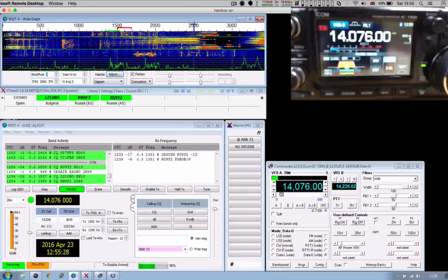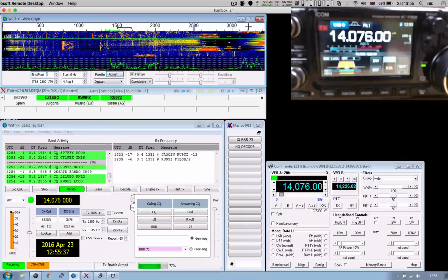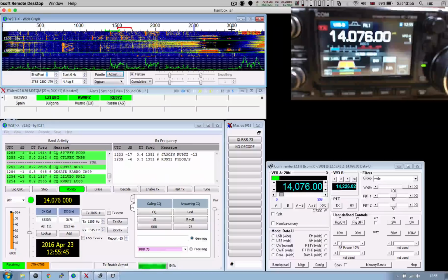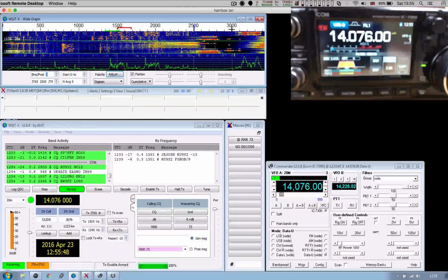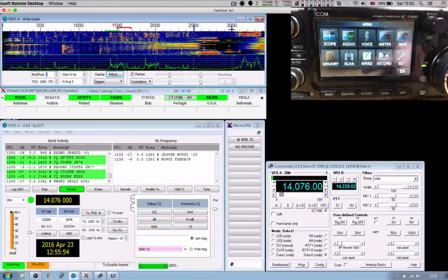So up to 2.5 kilohertz from the frequency we have JT65, over here JT9 signals. The trick is, what is our transmit bandwidth? Because if we try transmitting here, being tuned to 14076, will the signal actually go out? The short answer is no, it will not. So I tried and didn't get much luck with that, even on JT9.